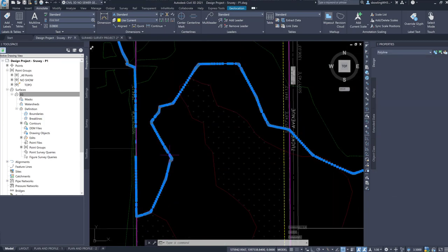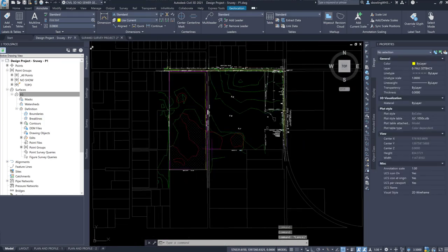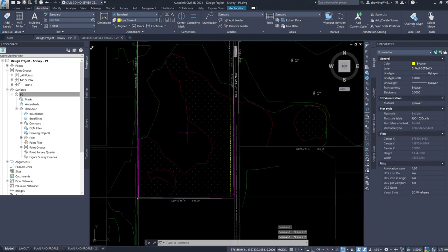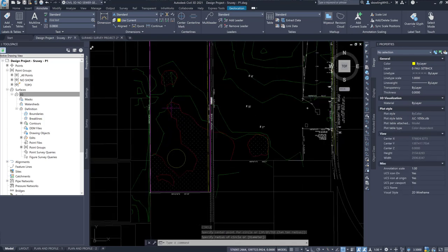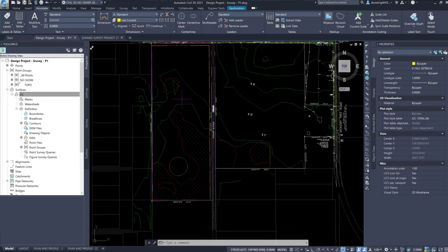So this elevation is 74 and this elevation is 73. So right here is where I would put a pond. If I had to draw, and I'm just going to do it schematically just for talking points, you're going to put a pond somewhere in here. Okay. Now, that tells you that your development is only going to be up in here.